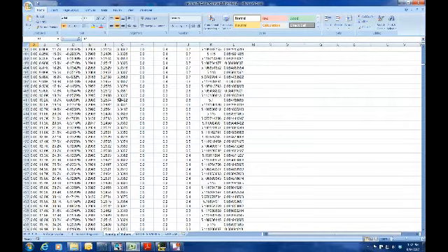So we can see that here's our spread over worst case. That's extreme value analysis with a nominal of 3.3. So that's how we can use this program to quickly find standard value resistors for a particular voltage divider.